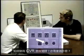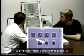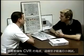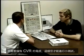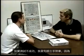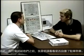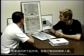How would you use the CVR erase switch? You just have to be on the ground with the parking brake set. What about the CVR test? You need to be on the ground, parking brake set. You need to have power to the CVR so that it can do us a little test. If I didn't get the test to work, I'd first check the parking brake, because maintenance might have chocked the wheels and then released the parking brake. So before I called them, I'd look down to see if the parking brake was set. If that didn't work, I'd check the circuit breaker. If that still didn't work, I'd call maintenance.